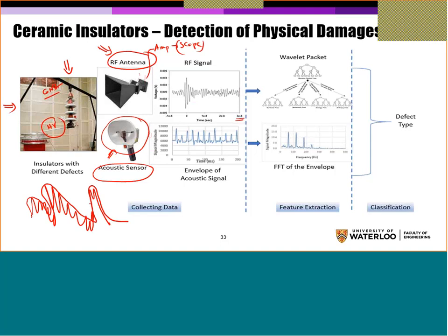And if you look here at the f of t, and this is the feature, you will see that this is our very low frequency. It's like 60 hertz, because the signal has been converted from a high frequency into an envelope of the signal, which is a very low frequency. And you can see we have only three features: the 60, the 120, and 180. However, here there are many features, many points.